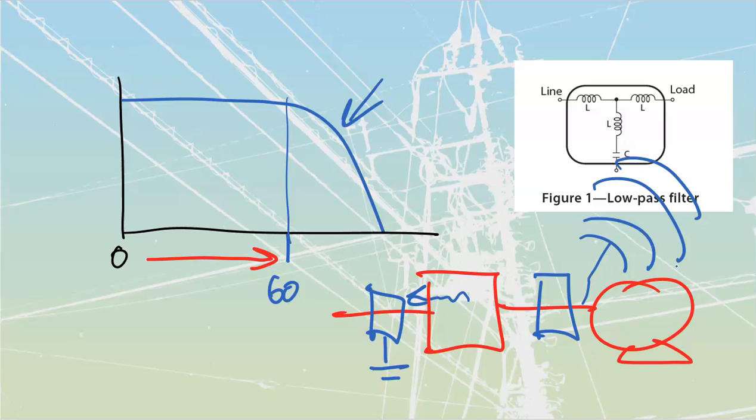And they're just reliable. You don't need to do a lot of analysis. If you've got a place that has a bunch of bad harmonics, and you know that those harmonics all started up after you put in a bunch of motors, maybe you can take a look around, but guaranteed that those motors and drives that you're looking at are where those things are coming off. So just throw these in off of the VFDs.